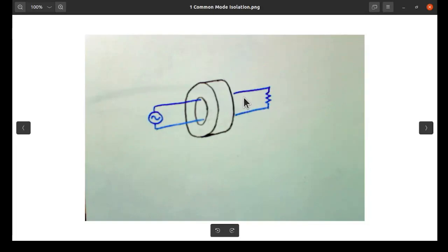Both sides are certainly conductive. However, at RF levels, the penetration of currents into metal is not very deep. And as such, the interior of the shield is principally an insulator, in the sense that there's no current flowing in it by virtue of what's in the other lead. In this case, the other lead is the center conductor.